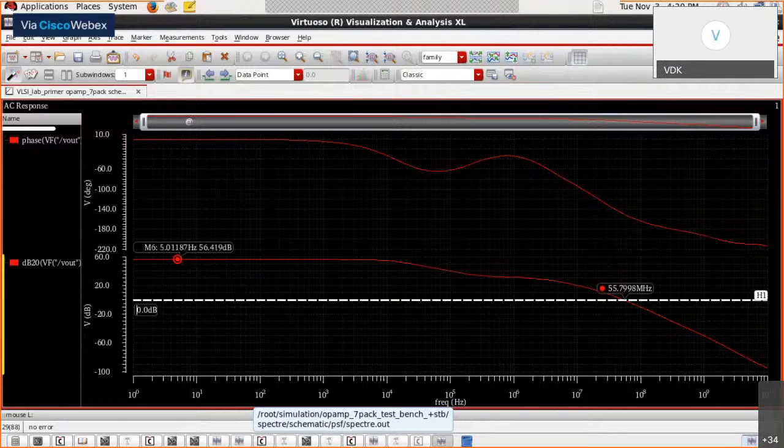Okay, sir. So it's a designer's choice. As I said in the morning, for every set of specifications we actually end up designing 3 variants of the circuit, and we tape out all 3. Then we look at which one works best. Typically for critical applications, we pick the best one. So it is iterative, because devices are so complicated.